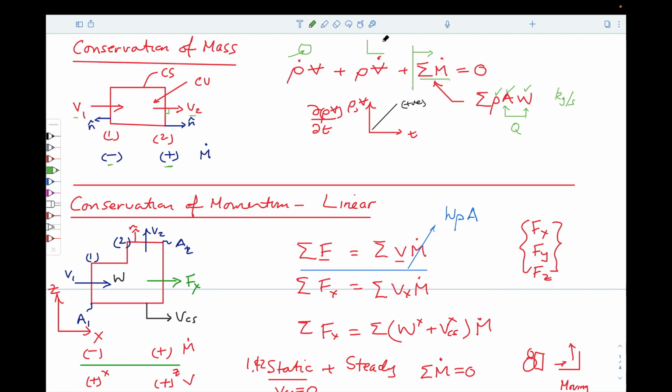And so the second condition would be where, for instance, we're filling a volume and the height of the fluid free surface rises as a function of time, and as a result of that, the volume is changing as a function of time. Again, we have to define a sign convention for this, just like these flow rates in or out. And the sign convention is that density or volume increasing with time gives us a positive quantity. So we have to be cognizant of that full sign convention.